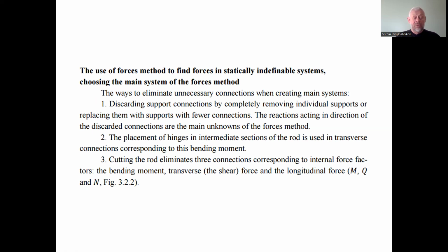Okay, the second, the placement of hinges in intermediate sections of the rod, is used in transverse connections corresponding to these bending moments. And the third, cutting the rod eliminates three connections corresponding to internal force factors: the bending moment, transverse force, and the longitudinal force.